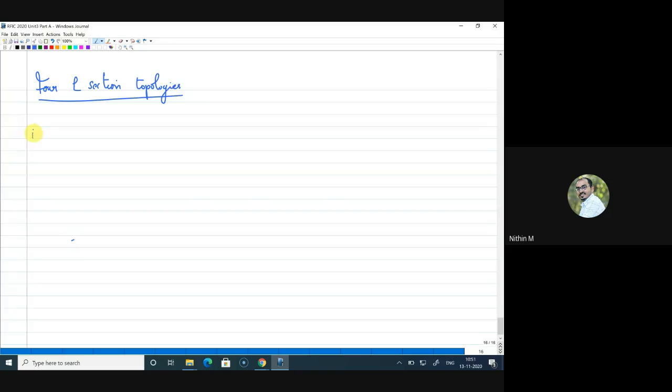So the first one is, I'll have a resistance RL. I'll put a capacitance here. Now the capacitance is added to transform the resistance value to a lower series resistance. I'll put it as RL, this is C1, and L1 is added actually to cancel C1.